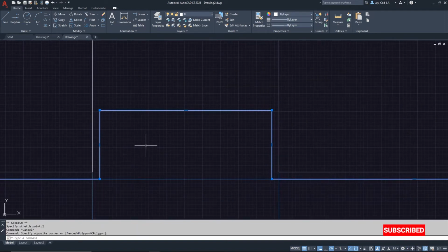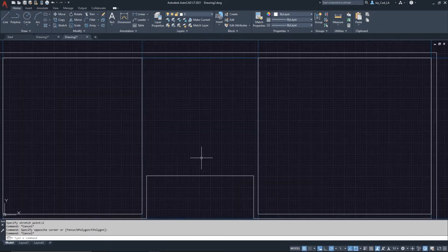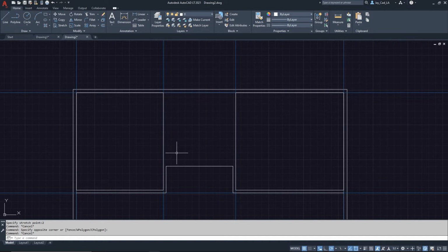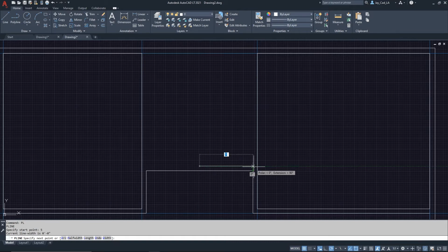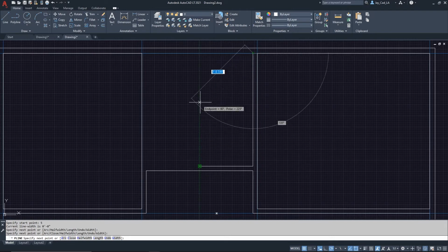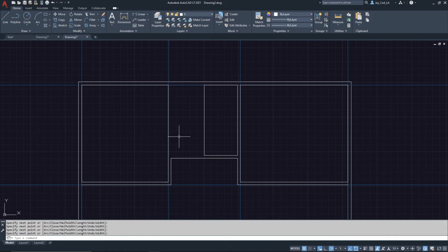Then let's select this line. I want to see how long is this. Instead of using the measure tool, I'll actually just select the polyline, and then by putting the cursor on one of the corners, I'll be able to see the dimensions that make that polyline. And you see this is like 10 feet right now, which is what I want really. So here let's do this. I'm gonna do a polyline from the middle. I'll go up by 5 inches, and then here reference to that point, then click here, then reference this one, and here we go. So now we have this.